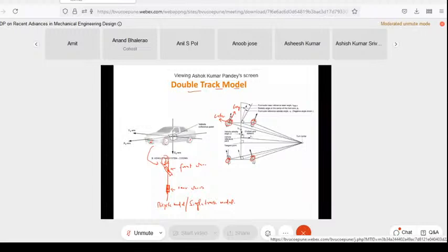So let us say this is your v1, this is your v2, this is your v3, this is your v4, and you see that all the four wheels are moving in different directions, right? Based on that, we try to find out another component which we call your slip angle. And based on the velocity, we also try to find out slip ratio, which will help us find the longitudinal force, and the slip angle helps us find your lateral forces and also cornering moment. I didn't mention that over here, but in the previous slide I was mentioning it. So that's what we do.